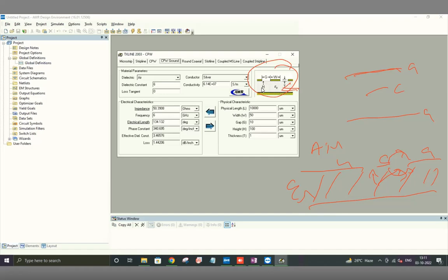So if you see that the circuit board has lots of holes in it all along the line, I don't know if you noticed that. Those holes are actually short circuits from the top to the bottom. There's a coating of metal on those holes, which connects the top ground plane to the bottom. So it basically connects this ground plane to this ground plane and then this ground plane to this ground plane, so that they are all now connected to each other and form one continuous piece.